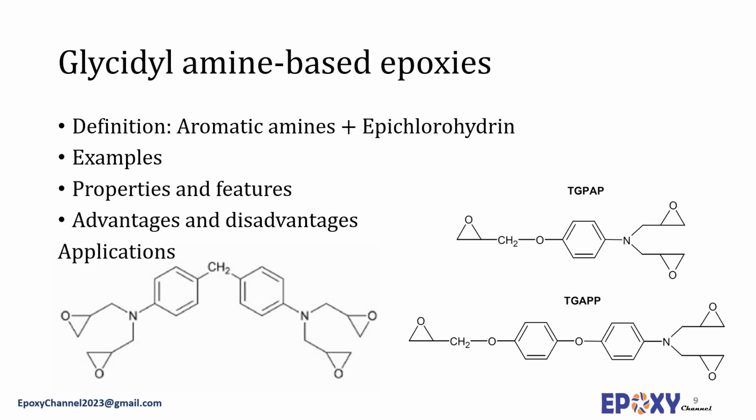However, fully cross-linked glycidyl amine epoxy resins are rather brittle, which limits their application when higher impact strength is required. To improve their toughness, GAAs are blended with thermoplastic resins such as polyether sulfone, polyetherimides and polyether ketones. Due to their low viscosity, they can also be used as reactive diluents for more viscous